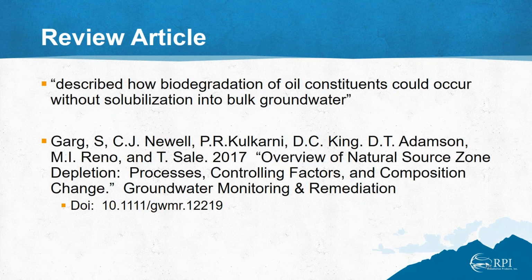Here's a question related back to the bench test. It's where I mentioned that BOS200 was placed in bottles with water. Was the diesel added to the test bottles as a free phase? No, it was not. If you recall during the presentation, I mentioned that we preloaded the carbon with diesel before we ever added it to the bottles. So there wasn't any free phase that was added.